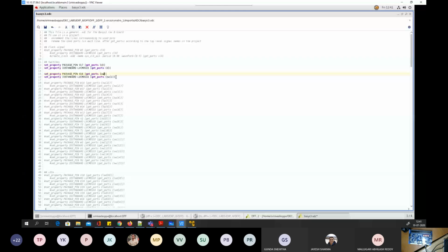So we have our RST signal. Please remember, as I said, Verilog is case sensitive, and our D flip-flop code has small d as an input and RST as input. Again we need to change this to RST. Now the clock signal: we said there are 3 inputs in total, D, RST and the clock.